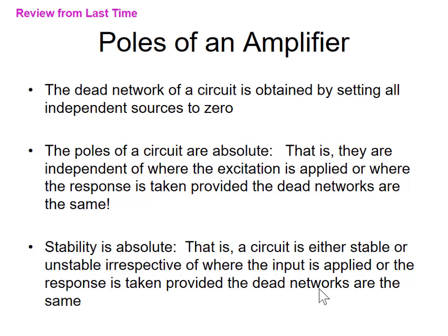We're certainly not going to exhaustively look at all transfer functions of a given circuit. If you have a circuit with 3 capacitors in it and half a dozen resistors and maybe 8 nodes, we could have dozens of different transfer functions for that circuit. And if we did that, all of them would have the same poles.